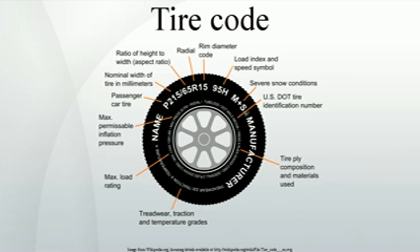To facilitate proper balancing, most tire manufacturers also mark red circles, for uniformity, and/or yellow dots, for weight, on the side walls of their tires to enable the best possible matched mounting of the tire wheel assembly. Tire geometry.